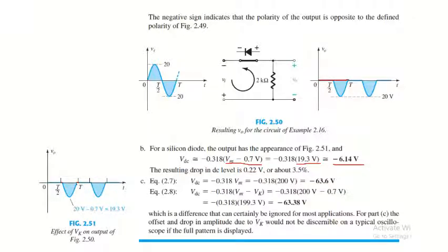So in case of the input signal, up to here, we need this value to reach the threshold value. Like this is 0, this is 0.1, diode will be off. 0.2, diode will be off. 0.3, diode will be off. When it reaches here, it is 0.8. So the diode will be in the on state, and we'll be getting an output value like this one.